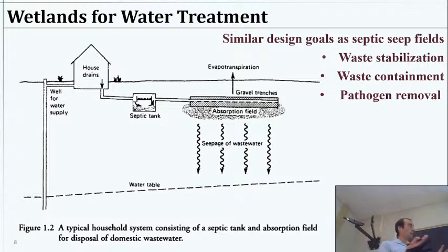If nothing else, let's say we protect a pond and use that pond as a treatment system and don't allow human contact with that pond, and we give a residence time of, let's say, 90 days. Then there's a good chance there's not too many human pathogens remaining by the time that residence time is discharging, right? Just even giving that amount of time will reduce the pathogen load quite a bit. It's not perfect, but it would be something.